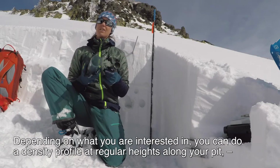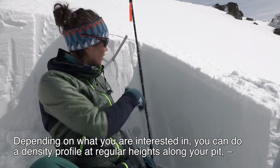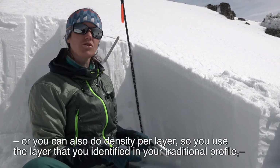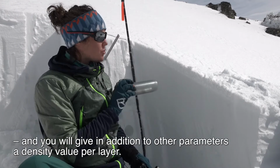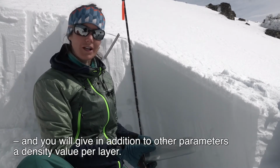You can either do a density profile at regular heights along your pit, or you can also do density per layer. So you use the layers that you identify in your traditional profile, and you give, in addition to the other parameters, one density value per layer.